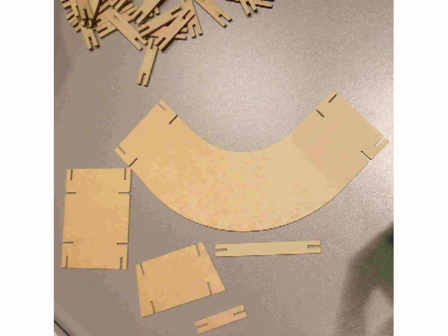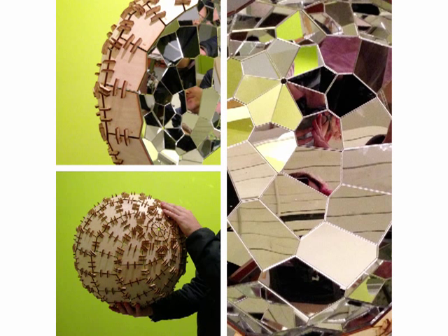And the method that I'm recommending, there's all kinds of ways to fasten these things together, and I think you've seen some stuff even in our own school with tabs that are folded or with bolts. I'm still kind of interested in the friction joint because it's about fabricating all the flat pieces that let you assemble this together. Okay. This is what I'm really talking about, though, something very close to this, where you've got pieces that fit between 2 facets, and they have an angle cut into them, so that the facets slot into it, and that maintains the angle.